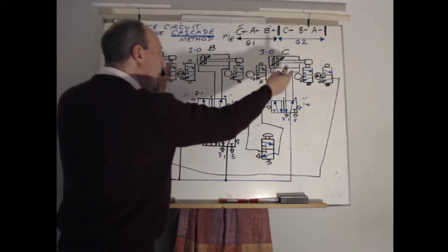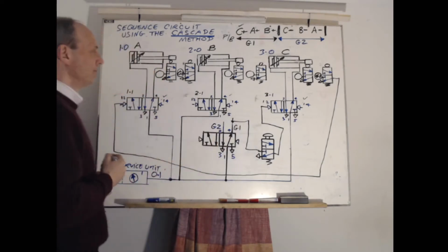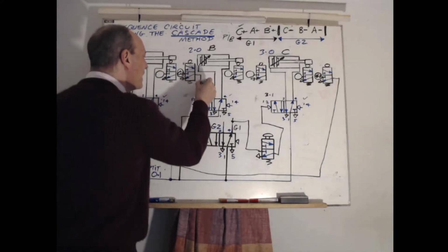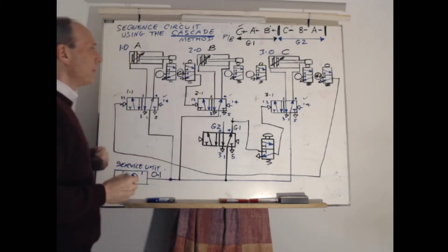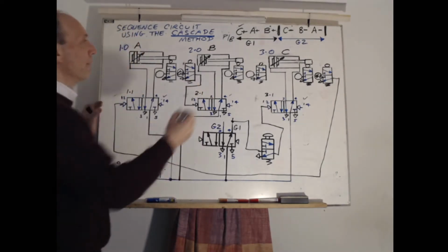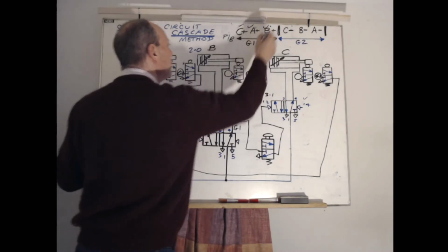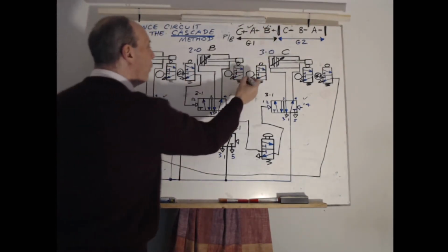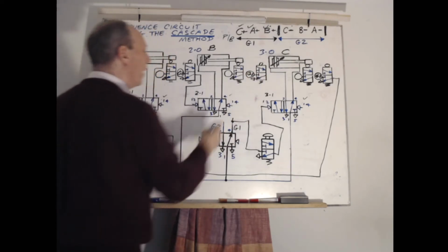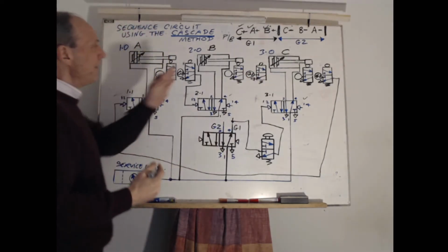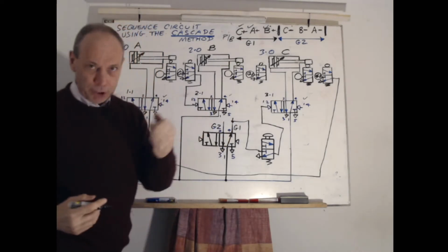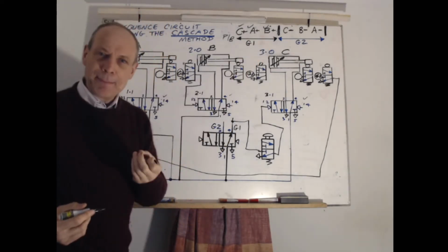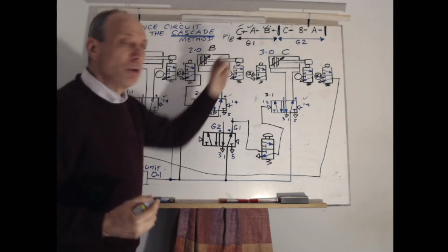So all the G1s are fed to this manifold. It hits the valve, and this valve then operates B, so B goes forward also. So B has now gone forward, and we've got all these 3 operations within group 1A. As this goes forward, this must also be on G1. It's taken the final signal of the B positive stroke, but we have the trap signal. So it has to eliminate the trap signal by eliminating its own grouping.